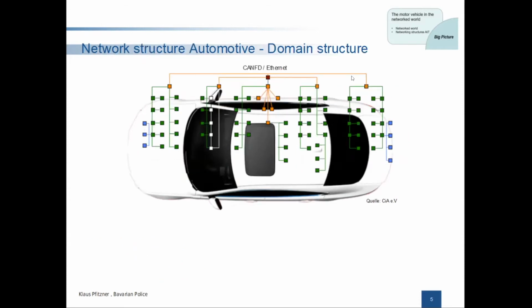Modern automotive networks are structurally divided into domains. In addition, the gateway also has functional tasks. Examples are intrusion detection and diagnostic function, which become much more important and have higher priority than before. With the introduction of backbone networks, the domains are also networked with a fast bus system.